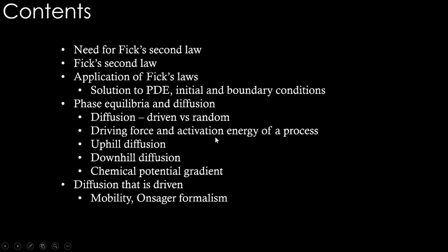Then driving force and activation energy of a process. Then understand uphill diffusion and downhill diffusion. All these ideas are basically going to focus on how the chemical potential gradient causes diffusion rather than the concentration gradient. And for such a diffusion which is driven, we are going to use mobility. Mobility we will be using instead of diffusivity, it is much more useful. In the next class we will talk more about that. Let's see them one by one.